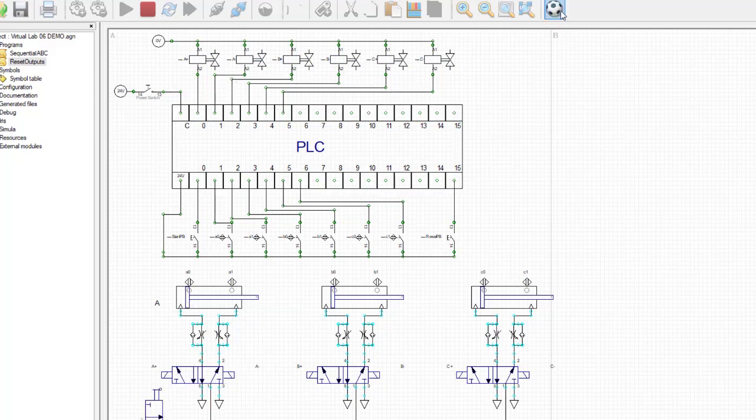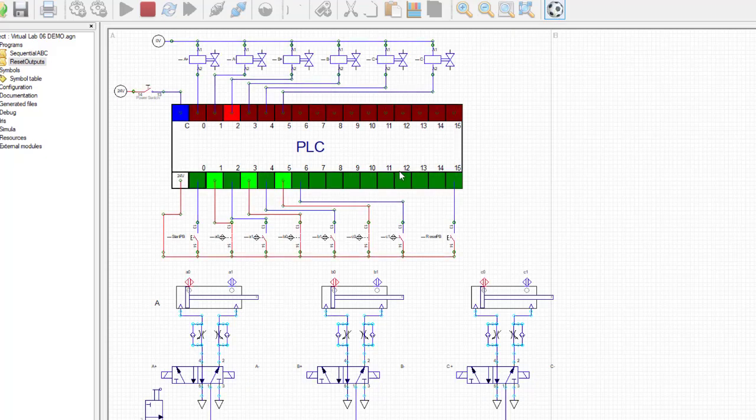Now this is where, when you restart the dynamic display, because we had that process kind of halfway done, you need to hit this reset button. That's why we put the reset button in there, so that we can clear the outputs, because otherwise you start it up and it'll be halfway in between the process. So do that first, then we want to turn the power switch to the outputs on and the compressed air, and just make sure that everything works.